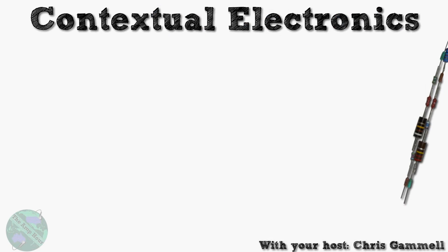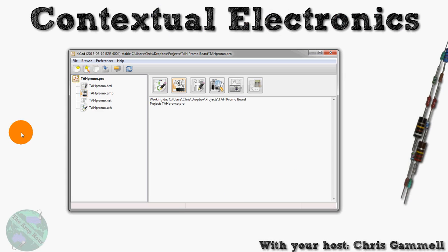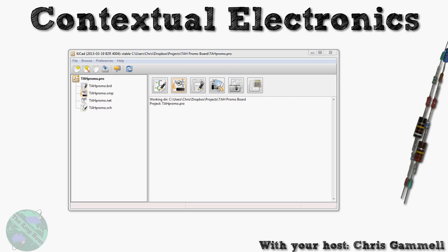But for now, let's just open up the KiCad launcher, and we're going to go into an entirely new program. Normally we've been working in PCB New, but we're going to go over here to Bitmap to Component. This creates an entirely new library from a bitmap. You can import a single file into this, and it'll create a single file library, effectively one footprint from one bitmap, and then we'll show you how to do the rest. To start with, let's look at the file we're going to use.